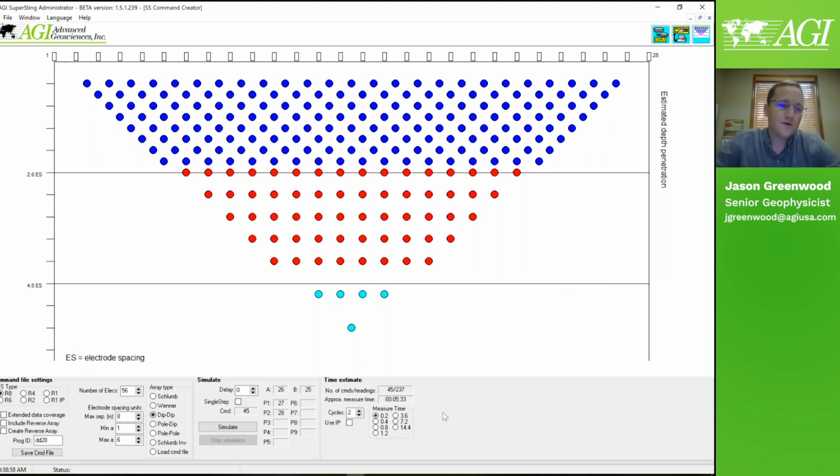And I would say that really what you want is resistivity, because once you're below the water table in the 100% saturated portion of the aquifer or the subsurface, your dominant control of resistivity is pore water conductivity and porosity, those two first things, because you no longer have moisture content to worry about because it's 100% saturated.